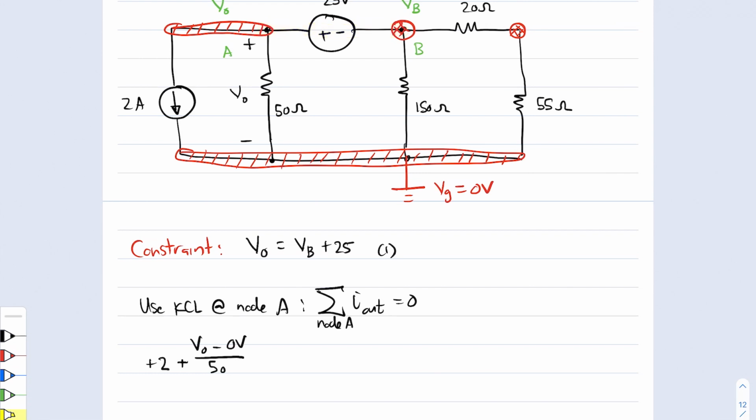We cannot use it. Why? Again, because that is not a resistor. It is a voltage source. So one of the things that we can do, when you don't know the value for something, is define it. What's running us into trouble is we don't know the current through that 25 volt source. So I'm going to define it to flow this way. I'm going to say this is I of 25 volts. So this is the current that's flowing from there to there.